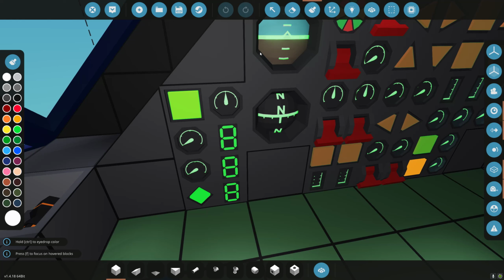We also have a digital three-digit display here. When we enter the waypoint, it's going to tell us what heading we need to turn to. Let's say we're facing north, 360, and the station is 090 to the east. The needle will be pointing directly to our right, and it would say 090.